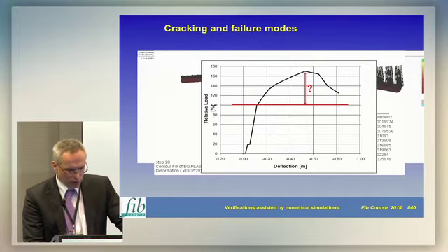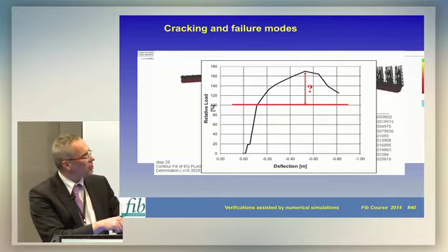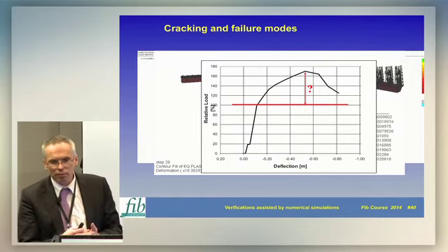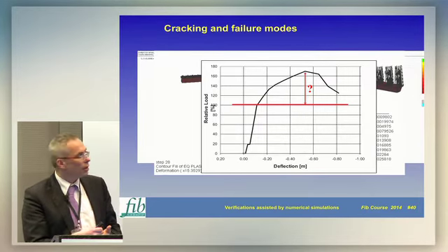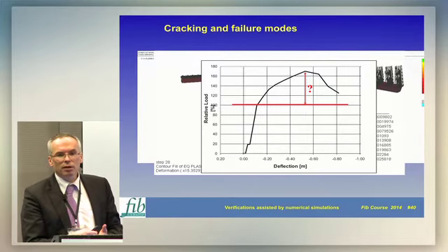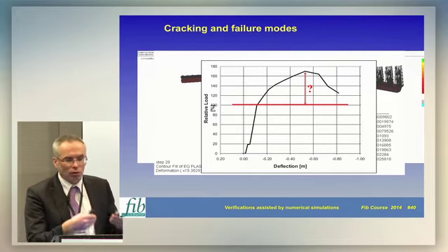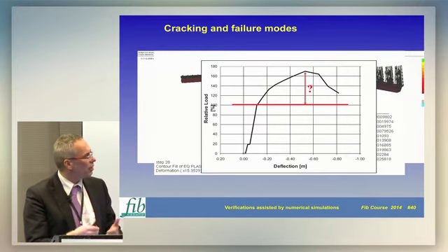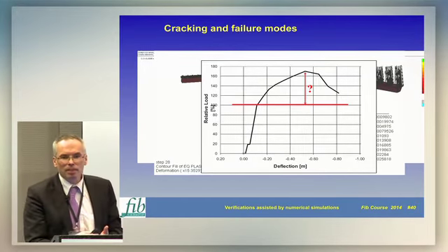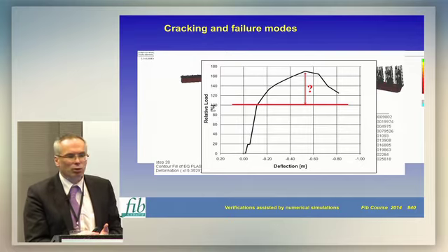And this is, again, this typical evaluation I told you. So in this global assessment, what it means is that for each load case, basically this kind of separate verification needs to be performed. So it is, of course, more demanding than classical linear analysis, where we can use with advantage the superposition of load cases and also superposition of calculated internal forces. In nonlinear analysis, it is necessary to check each load case separately. So usually it would be done for some critical structures and for the most critical load cases.